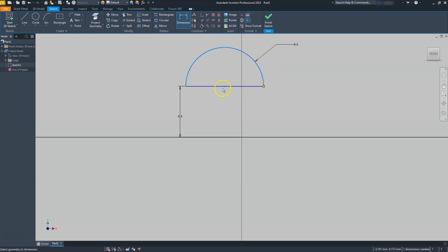All right, now I also want to move this in line here. So what I'm going to do with that is first check and see if this point is vertical to this one. So I'm going to select the vertical icon here, and you can see I get those dotted lines that are going vertical to my screen. I'll select this center point, and then I'll click that center point.